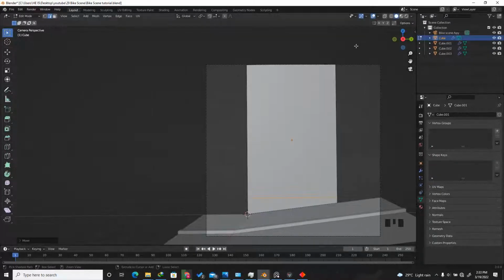And also I can press Ctrl R again. As you can see, when I hover around the horizontal part of the mesh, it's going to give me a vertical subdivision. And also if you scroll your middle mouse upward, it's going to increase the number of subdivisions that's placed inside the scene. So I'm going to scroll it until I have 3 subdivisions. After this, I'm going to click it. When I do that, as you can see, I can move them, but I can hit escape so that it will be placed in the center.